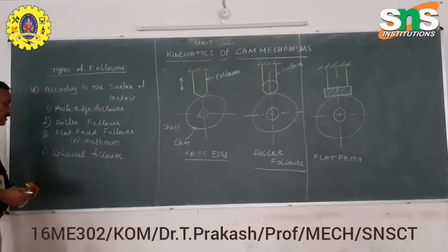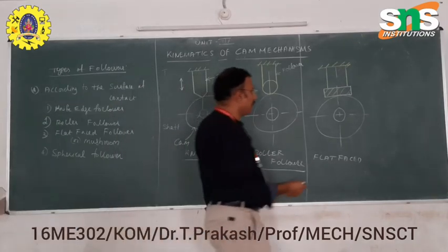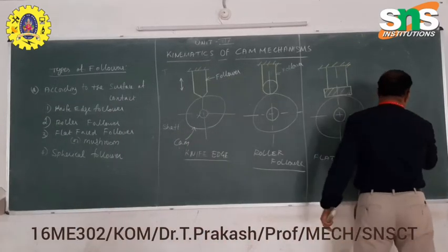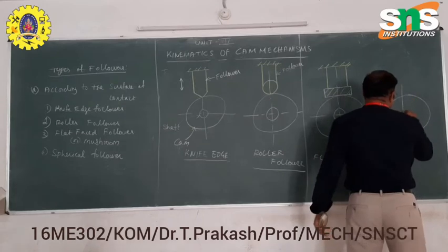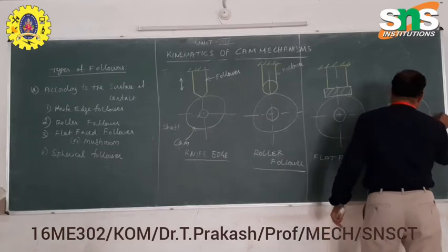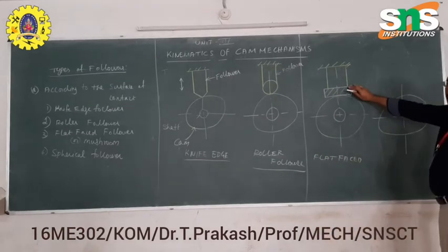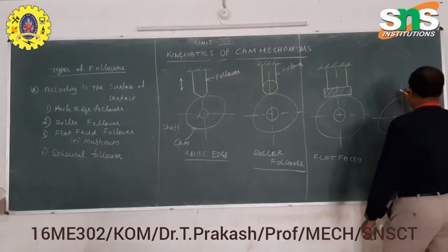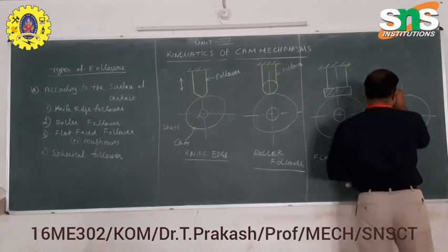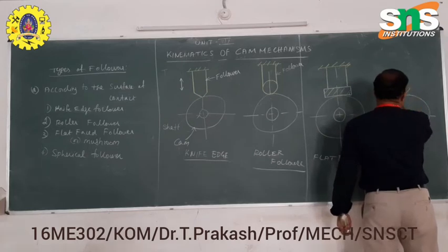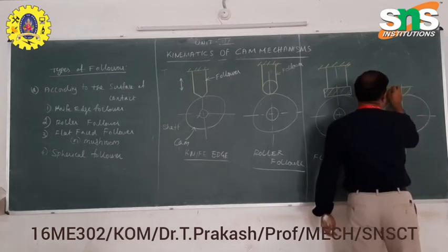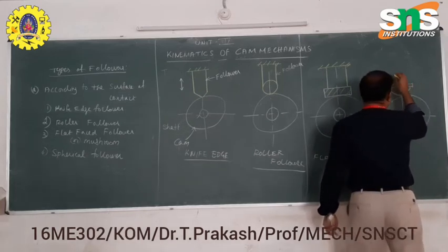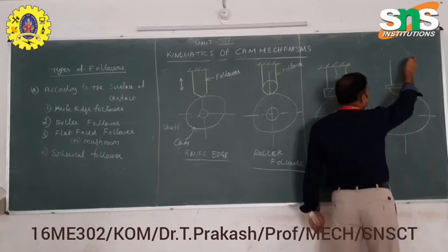Next, the fourth one is the spherical follower. What is the meaning of spherical follower? The edge face of the follower will have a spherical shape. Once again, we are changing this flat face into a spherical one, to reduce the wear and tear.